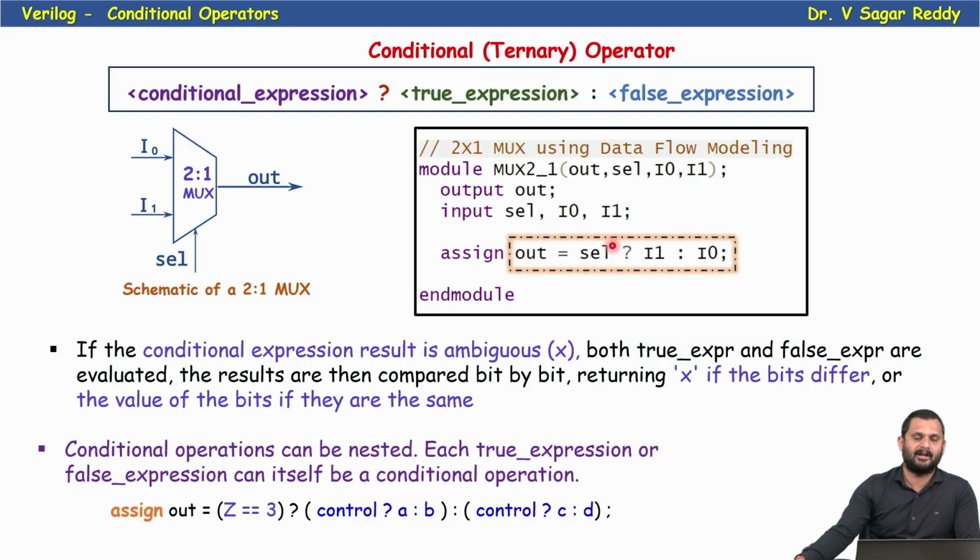In Verilog, we use if else only in a procedural block as a procedural statement, in always and initial. We never use it in a continuous assignment like an assign statement. But the conditional operator can be used either in a continuous assignment or in a procedural assignment. Also, we can use the conditional operator in the $display statement. We cannot use if else in the $display system task, but we can use the conditional operator in $display.